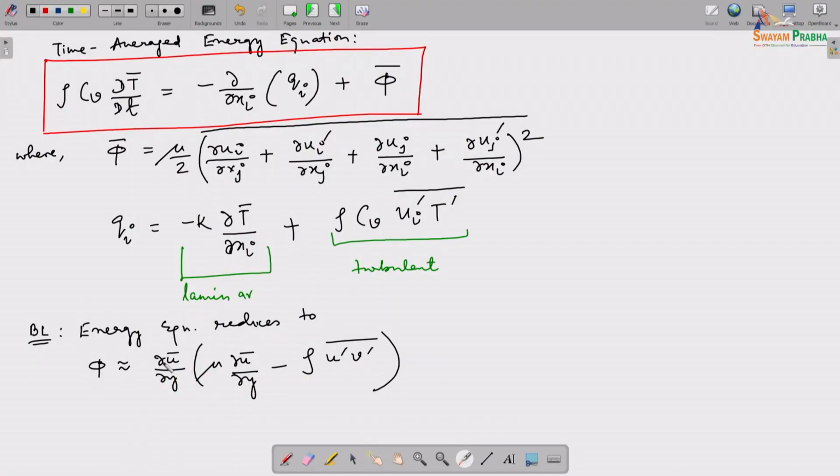That is why we have the term del u, because I am neglecting some terms. The change in the u component of velocity in the direction perpendicular to it, which is y, is not trivial. So that slope remains, whether we ignore others. And again, we also take the time average of the fluctuating part, which is u dash and v dash.